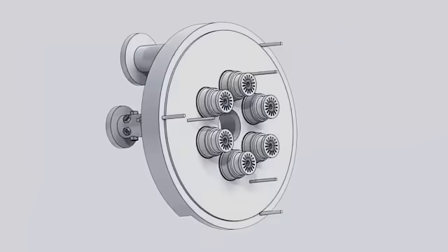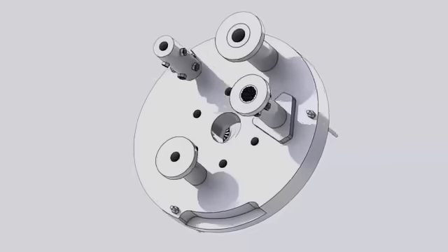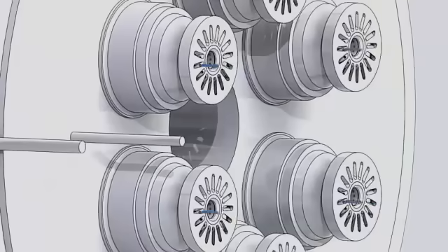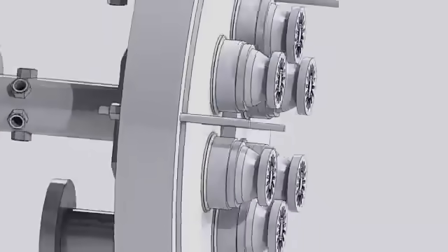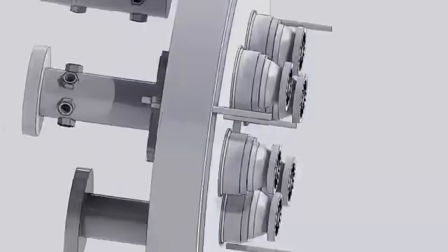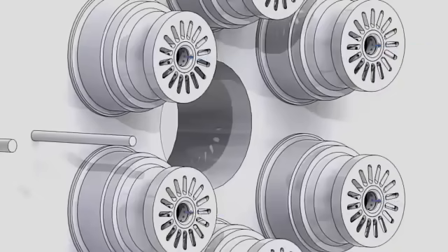Fuel is injected into the liner primary zone through 6 identical nozzles. Gas fuel enters the primary nozzle's assembly through the fuel gas connection flange and is routed through internal machined passages to the orifices located in the gas tips. Atomizing air is introduced in the same manner through internal passages and exits to the primary zone through multiple holes on each of the gas tips.